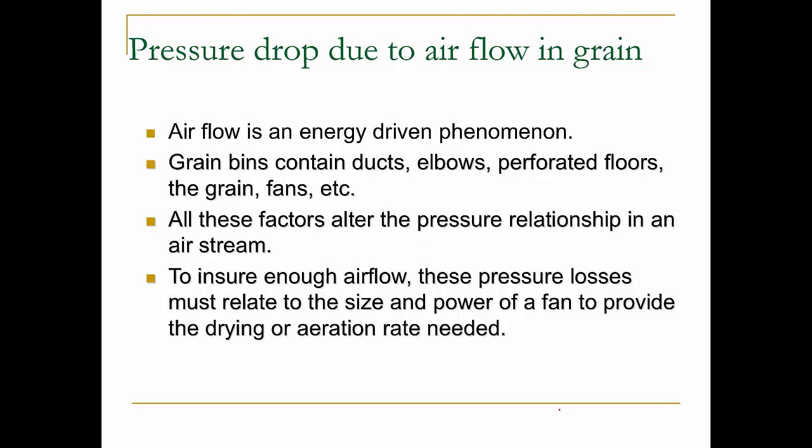So, pressure drop due to airflow in the grain. We talked about airflow. Airflow is an energy-driven phenomenon. The way a grain bin works is, you have a perforated floor, like a screen, over which you fill the grain. At the bottom we call this a plenum chamber, or the air chamber, and you connect a fan, and the fan builds a pressure, and then the air goes through the grain bin, right? There is ductwork there, and there might be some elbows, there is a perforated floor, there is grain, and all of those things are there, okay?